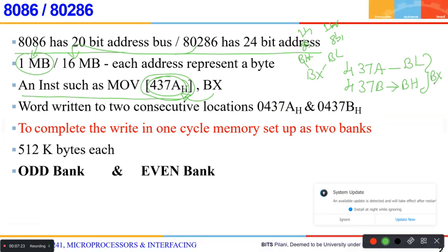One location in the memory can take only 1 byte. So whenever the microprocessor writes data into the memory, it will take 2 locations. Yes or no? And those 2 locations are taken from different memory devices. Just try to remember this. That's where I spoke about the mismatch between a single memory and an 8086 microprocessor. Try to understand this concept.